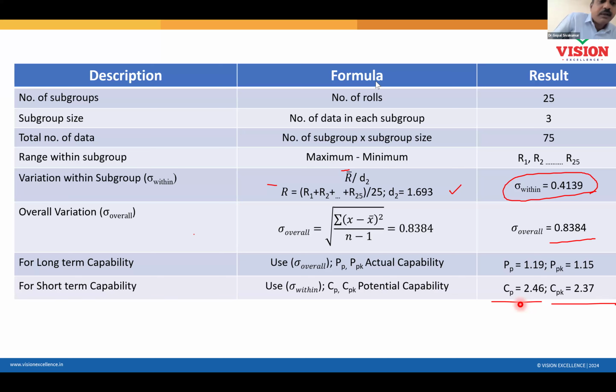Maybe possible. You have to conduct the capability study very frequently. Every week you may have to conduct the capability study. If you are happy, go. But if you just want to study the capability in one go and take a decision, now it is better to look at Ppk.